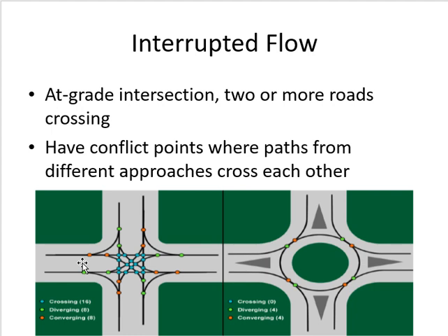Okay, and these two pictures also show you the conflict points for an intersection without a roundabout. This one is with a roundabout. So you can see there is no crossing basically. All crossings are gone. The only thing remaining with the roundabout is right turning. So I'm right turning onto the roundabout or off the roundabout. This is onto the roundabout, this is off the roundabout. This is the only thing which happens, and it happens on all four sides.